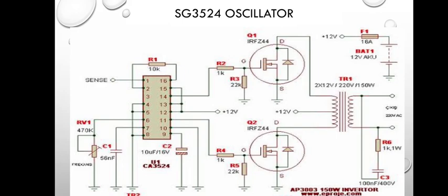Then pin 6 and pin 7 are one of the most sensitive pins in this IC. You can replace the variable resistor at pin 6. You can leave that at 470k or 500k, and you adjust it to get your 50 hertz frequency.